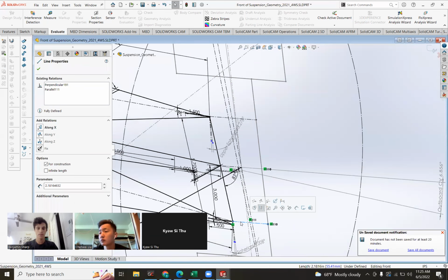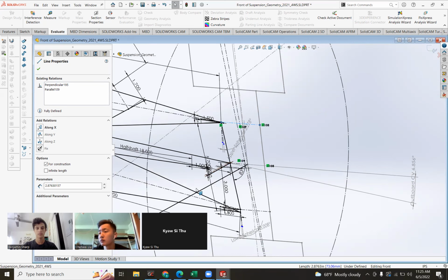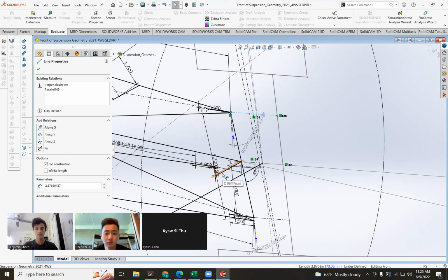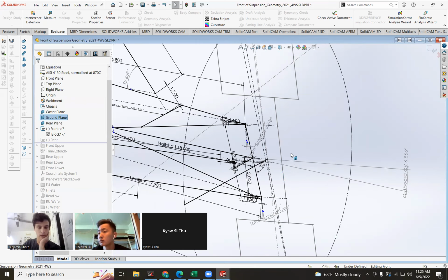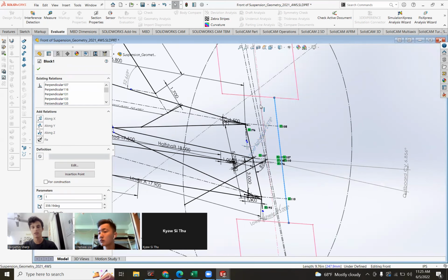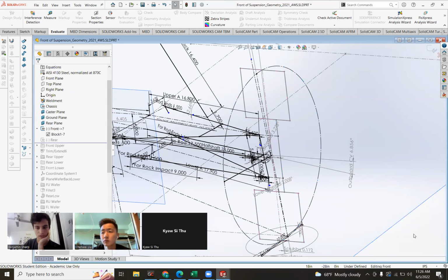And you do that by drawing these other lines that run out to it and have perpendicular mates to it, so that when these turn, they're turned by the turning of the steering arm, basically, because they're perpendicular to the steering arm. So the steering arm pivots when the tie rod changes length. That steering arm causes this to pivot because it's a perpendicular mate, which causes this to pivot because it's a perpendicular mate. But yeah, this line right here, which is the pivot line of the wheel, this line, which is the center line of the wheel, and this line, which is the diameter, those are the only important ones, really.